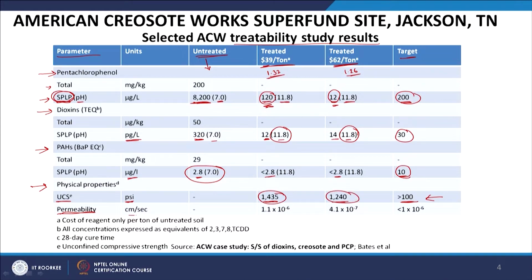And again permeability, it has to be less than 10 power minus 6 centimeter per second, right. I guess this does not do a great job in that regard, right. This one yes, to some extent, right, but it is not near the relevant standard by a great degree though.